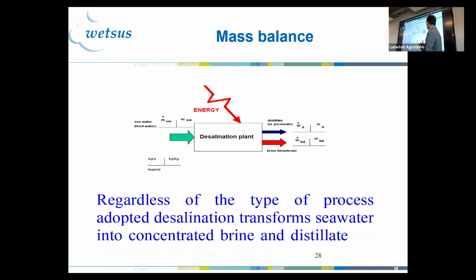stream. So you see here a diagram that I used in one of the courses I did on thermal desalination, actually in Spain, in Almeria, where they have a very large solar platform. You can see that the blue arrow is much thinner than the red arrow, which indicates that normally your brine fraction of volume is larger than your permeate. And that is really the case most of the time in thermal systems. In reverse osmosis systems, as I said, it can go 50-50, depending on your initial concentration.